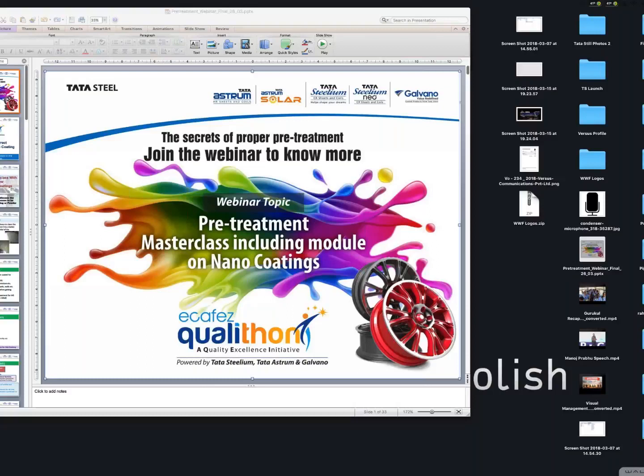Sometimes shiny crystal structure is formed. Yes, I've seen that. But most of the time, your phosphate layer is thicker, and those are very big crystals which happen, and that will definitely affect the paint performance, because too thick a phosphate coat also is not very good.